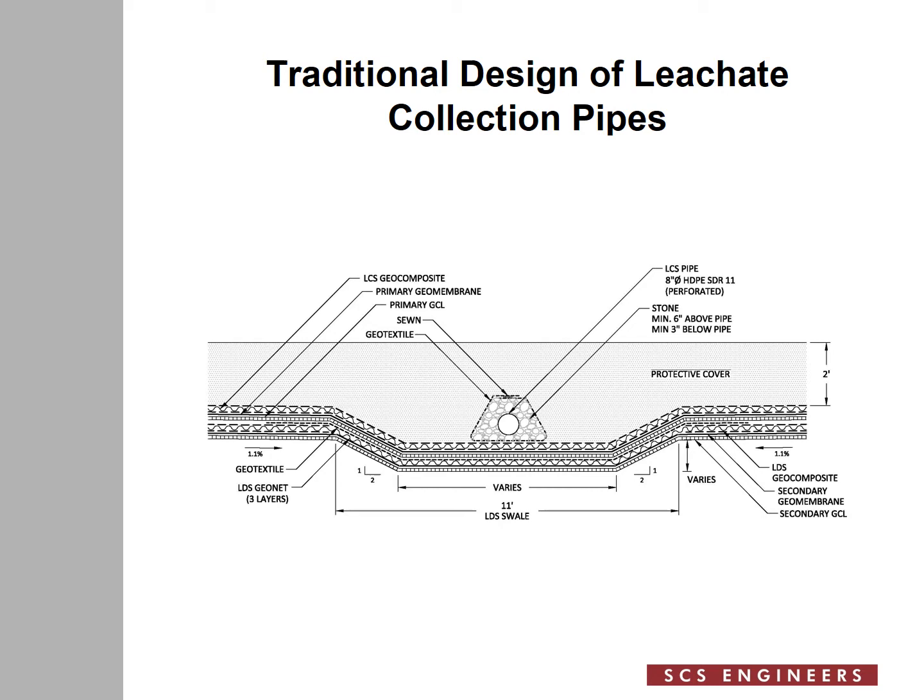If you think back of the rule of transmissivities, the flow of liquid out of the geonet through the upper layer of geotextile doesn't meet the rule of transmissivities. In the next slide, I'm going to go step by step to show you from what medium to what medium the leachate flows, and we get more into the details of it.